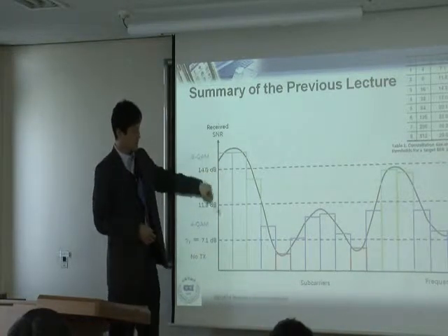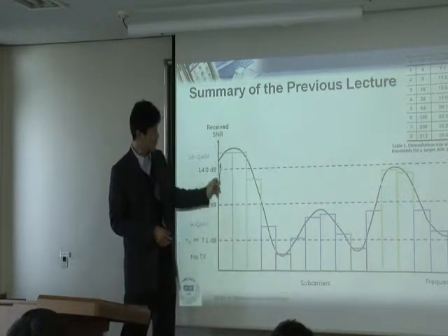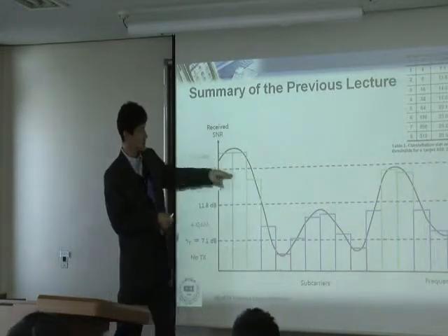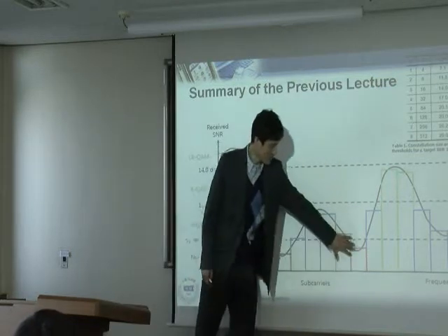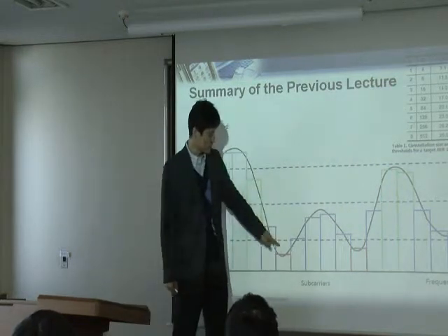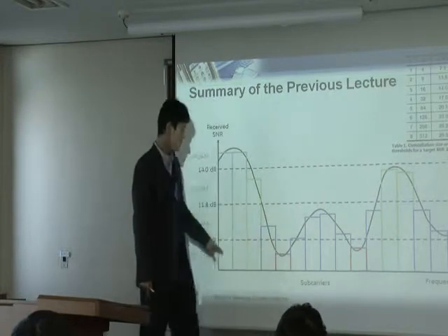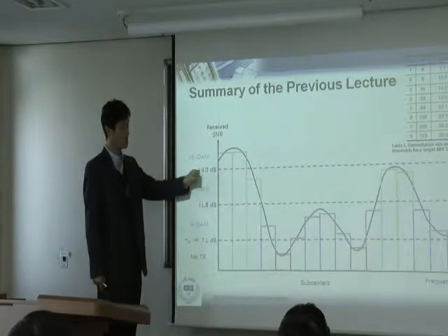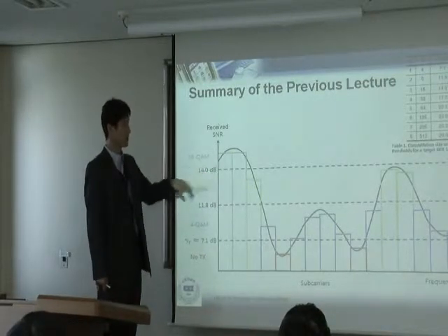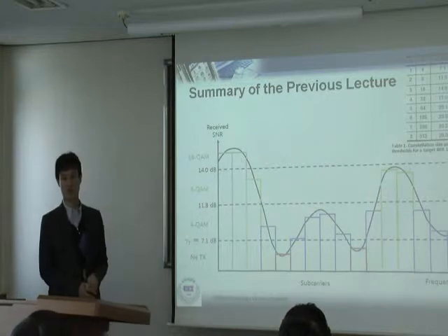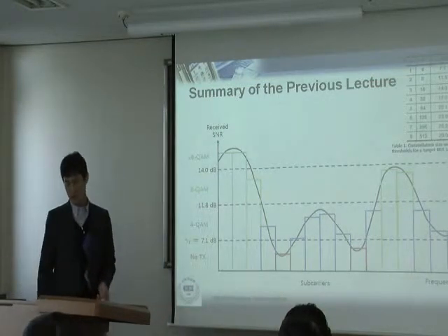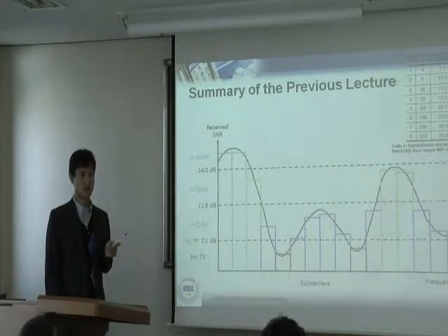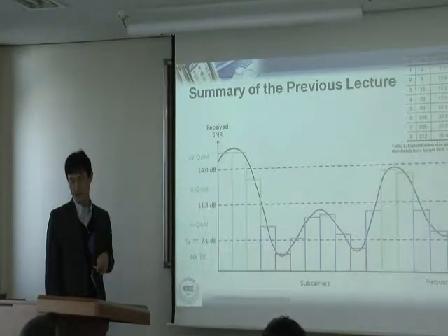Okay, for some subcarriers, some of the frequency range, you have a high channel quality, so therefore you can have higher modulation. For some other subcarriers, the channel condition is low, so you have a low modulation. So depending on the channel condition of that particular subcarrier, you can allocate different modulation. So this is very popular. In fact, every OFDM system has this adaptive modulation together with OFDM.